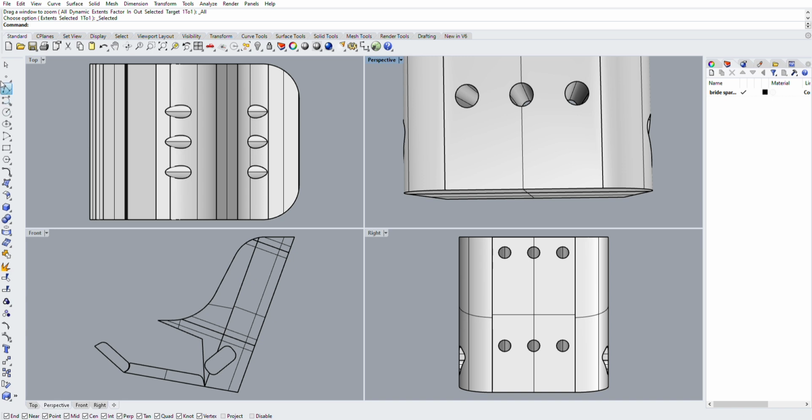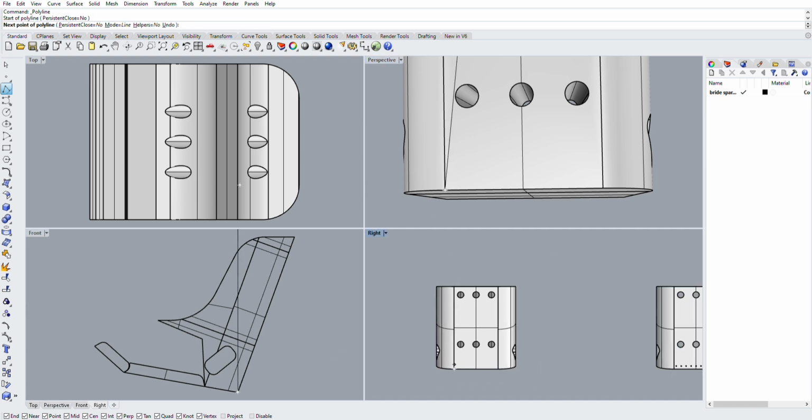Now on the back, we know the rivets don't come past the bend, so I can just draw a simple line. I can round it over. All I'm doing is bringing it up 1.25 inches, over 10 inches, because that was the width of our straight section, back down 1.25 inches. And then I'll draw a random shape out beyond this.